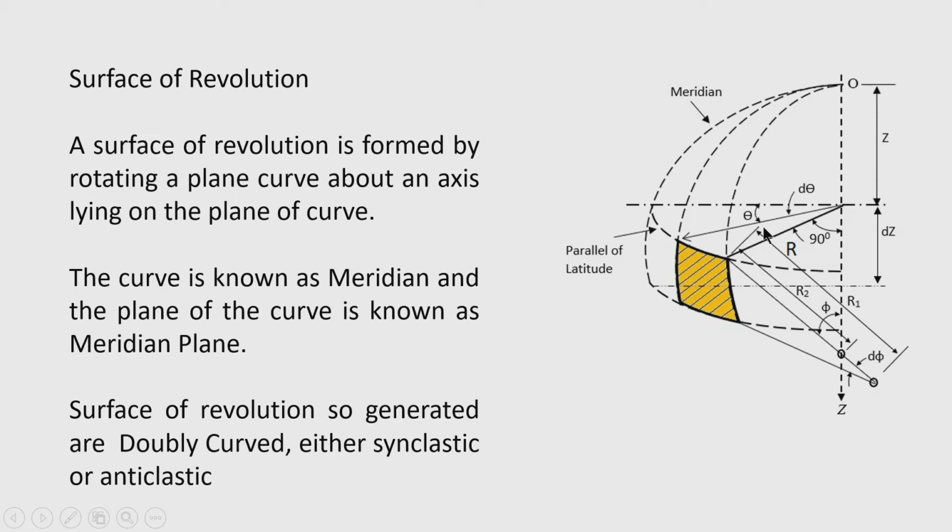Now, here you are seeing that an element of the shell is taken, which is shown by a yellow curve, and then with reference to some axis, here the horizontal x axis you can call it, an angle is measured, which is known as the circumferential angle, to locate the position of any point P. Because this distance is taken as small, the position of a point on this arc is defined by this angle theta, that is the circumferential angle, and also this meridian.